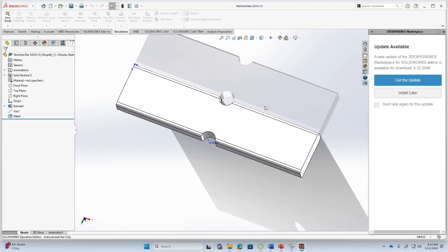So the type of analysis that we are going to do today will be a 3D finite element analysis, because that can be done quite easily in SolidWorks. But keep this in mind: if your part sizes become larger, then this kind of analysis will become computationally very heavy. And although our lab computers are quite powerful, even they start to struggle. But not so much for this small part that I'm going to demonstrate right now, okay.